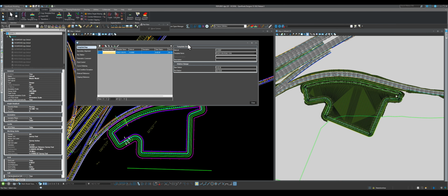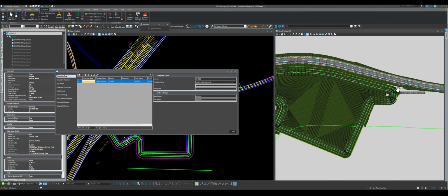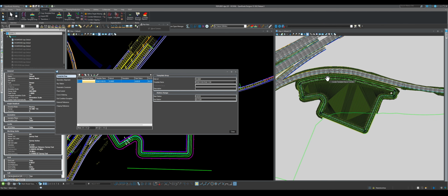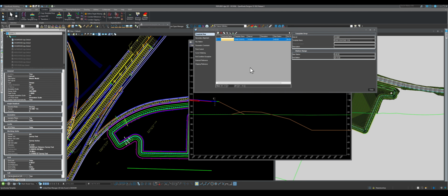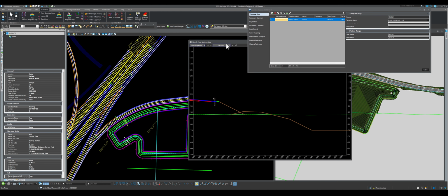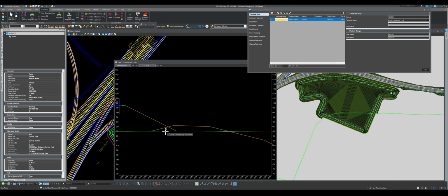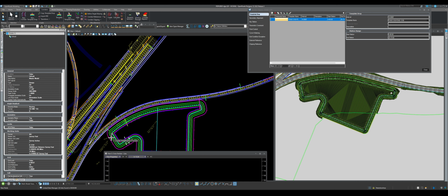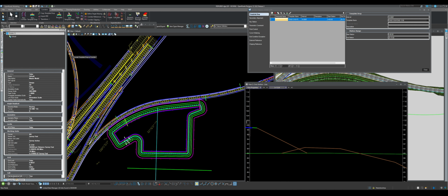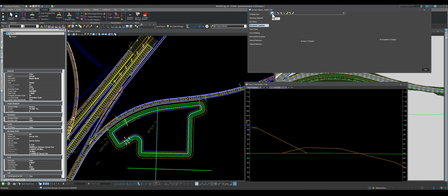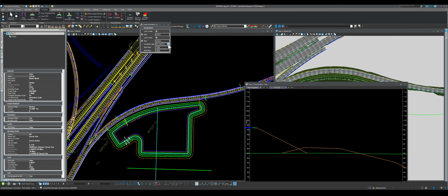So now, I don't want it to be everywhere, right? I want it to be off here because I want the roadway to deal with that, right? So let's open the cross section and you can see it's already made this. But like I said, here I want it to be off. So how am I going to turn it off? By doing the following. Go to parametric constraint and then click on add and new, and then you go here. You're going to see all your switches.